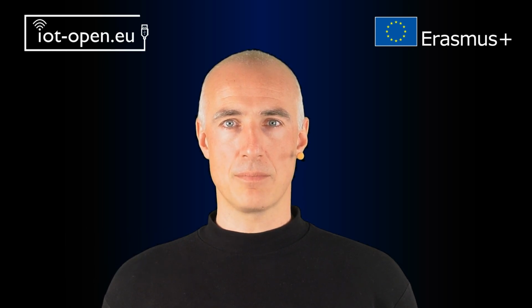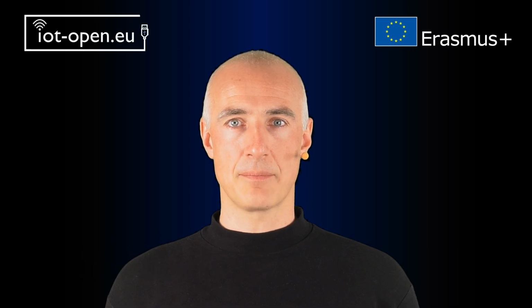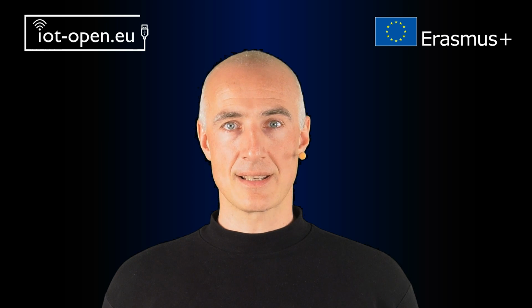In this lecture, we present how to handle various input devices connected to the Raspberry Pi board using Python language. Some sensors require importing of additional libraries that implement communication protocols, as in the example of the DHT temperature and humidity sensor. Simple sensors, like in the example of a button, use binary or analog values to present their state, so we can use them straight.